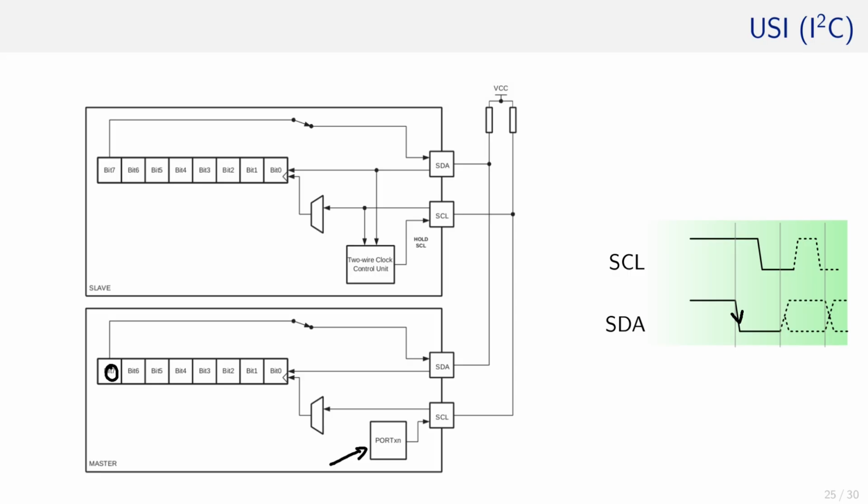Which is then followed by the toggle of SCL to 0. It is important to keep the order intact so as not to violate the protocol specifications and to make sure that the I2C devices on the bus understand the protocol. As you can see, the developer has to manually drive the wires to create the start condition, as this particular condition is not in the common denominator and hence not included in the USI specifications.